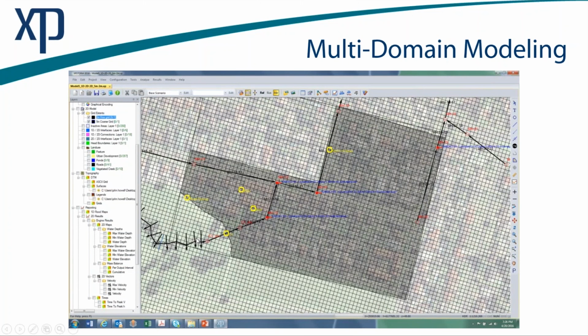So now we're going to have flow through the channel, over banking, and entering the village. And once it enters the village, we've got the fine grid, which is going to give us a lot greater level of detail in terms of looking at what's actually happening. It will allow us to see the flow through the buildings and so forth. Along with that, as flow enters this more finely gridded mesh, I might want to crank the time step down. So we have tools for treating the time step differently between this more sparse mesh and the fine mesh in the center.